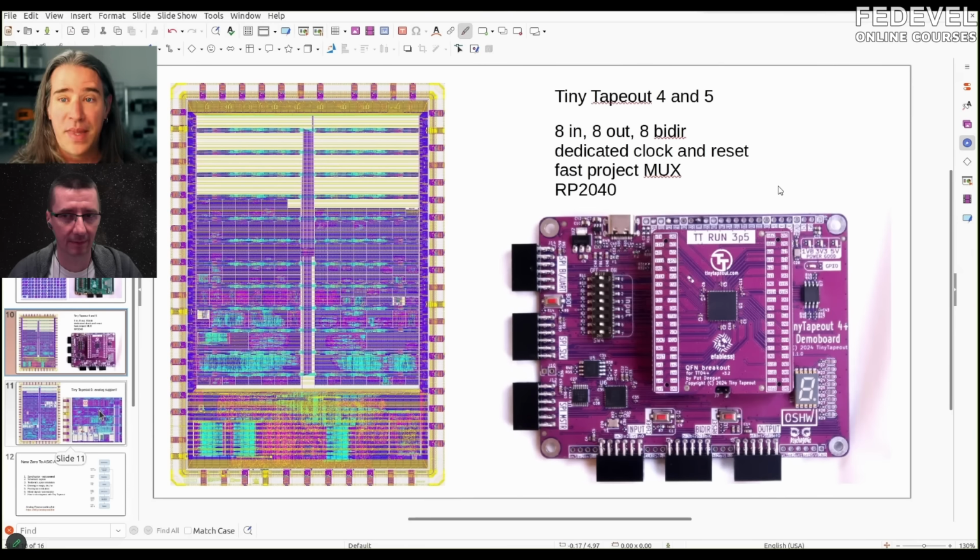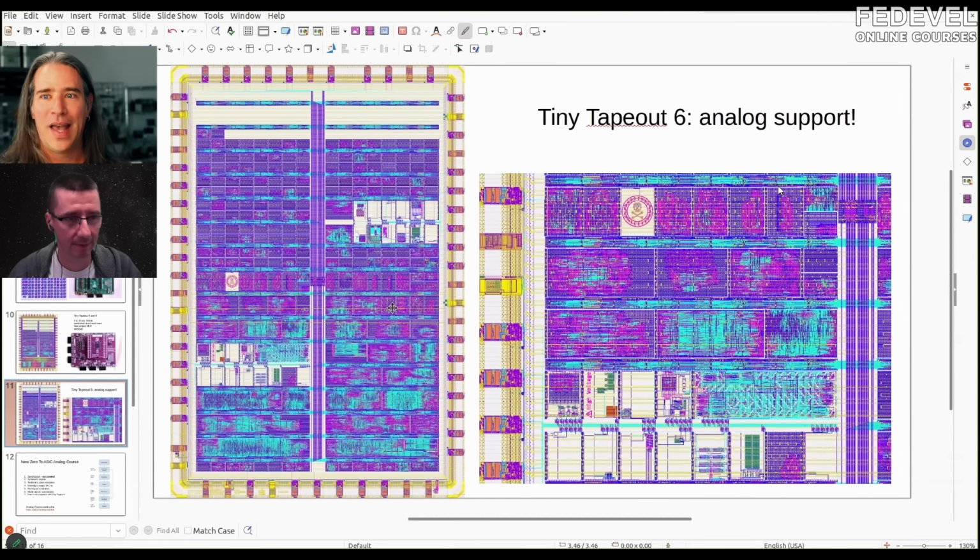And so then finally, with Tiny Tapeout 6, Analogue came into the picture. And with Analogue, you see these squares that are all full, that's machine-filled squares. Because when you do a digital design, let's say you only take a little bit of space. Well, the system will fill up the rest with filler, decap, bypass capacitance and stuff like that. Whereas if you're doing analog design, you'd have to do that if you want it. So these squares that look more empty or that are designed funny, like this guy here, that's Uri's fetish for skulls. But the point is you could do pretty much everything. And down here, the Psi ADC, that's mine there.